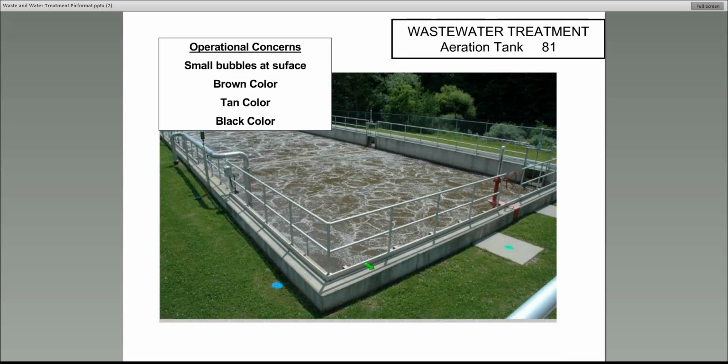If you go through OSHA training, you'd go down to the bottom of the tank and get into a crouched position and bring yourself up to the surface. And if hopefully you're close enough to the rail, you have to look for where the closest rail is, move around and crouch again and get to the closest rail. People have died in these tanks because they slipped and fell in. They didn't know how to get out.